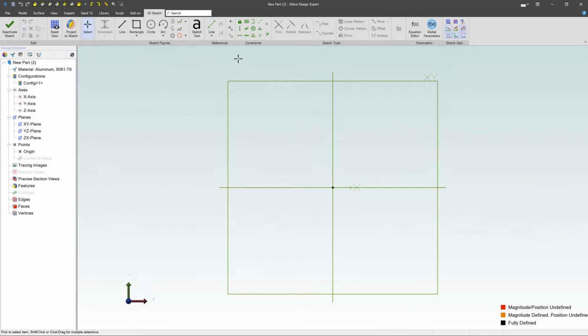I'm going to go ahead and grab a sketch tool. Now notice up here at the icons where this ribbon changed over to our drawing tool. So I'm going to use that rectangle tool here. I'm going to go ahead and snap to the origin and then draw out a rectangle. All right, once I have that, I can actually hit the space bar, which will bring up this little in-context menu. And sometimes if you just click, it comes up as well. But go ahead and choose the extrude feature.